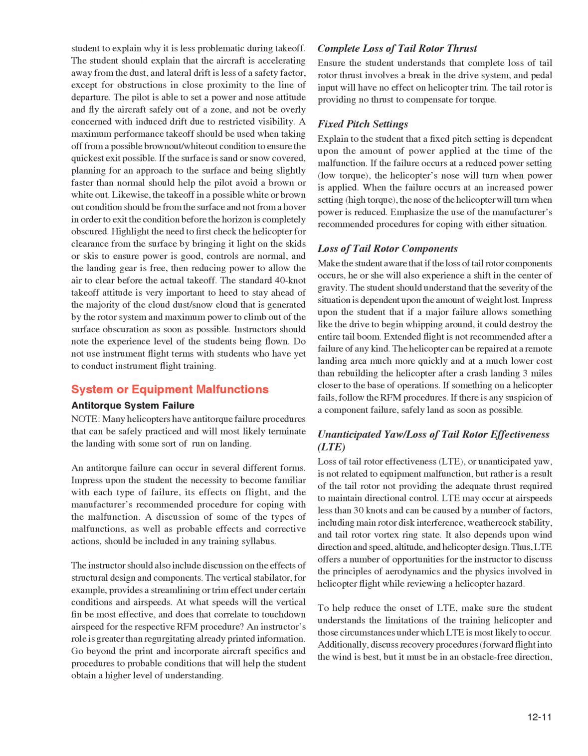Fixed pitch settings. Explain to the student that a fixed pitch setting is dependent upon the amount of power applied at the time of the malfunction. If the failure occurs at a reduced power setting, low torque, the helicopter's nose will turn when power is applied. When the failure occurs at an increased power setting, high torque, the nose of the helicopter will turn when power is reduced. Emphasize the use of the manufacturer's recommended procedures for coping with either situation.